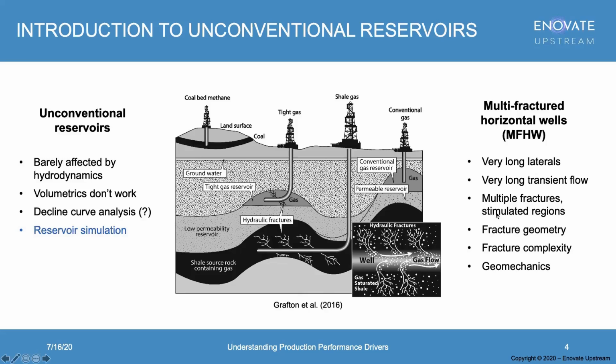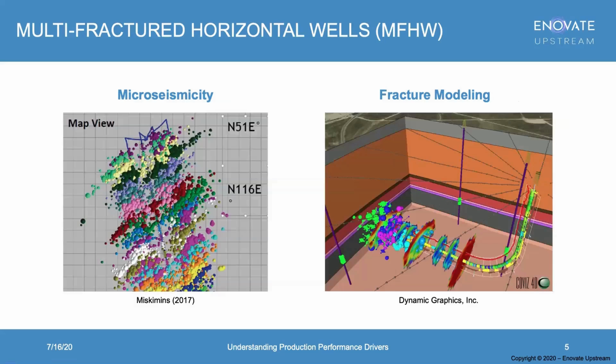The micro cracks that happen around the main hydraulic fractures are unpropped, so they are more prone to close faster as we withdraw pressure from the reservoir. So geomechanics might or might not play a role. In particular, this is the case for high pressure formations like the Haynesville in northern Louisiana and Texas, as well as the Vaca Muerta Shale in Argentina. Those are two good examples of geomechanics having a large influence on well performance.